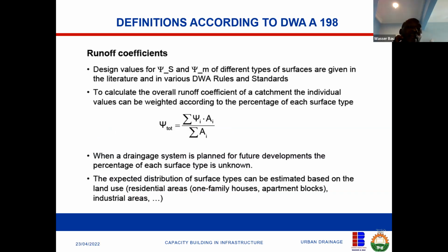So now, if you have different catchments that have different runoff, it means you take the average. If I come to a place like Gariki, there are some places that are roof, some places are road, some places are residential areas, some places are gardens, with different runoff coefficients. So I need to use what we call the mean weighted average. It is like an average, but the plain average is not a good representation of what is happening. Average just gives you an average value, but the mean weighted average will give you a value based on the components that have a higher weight.